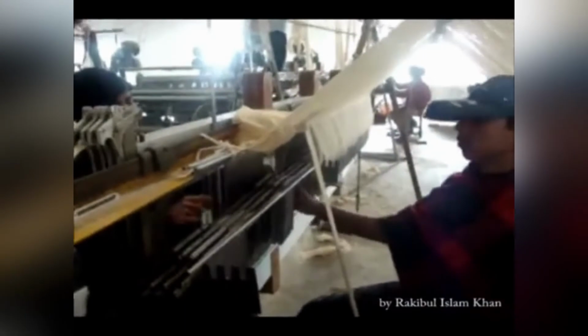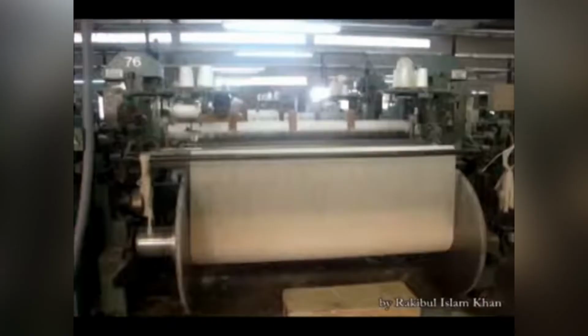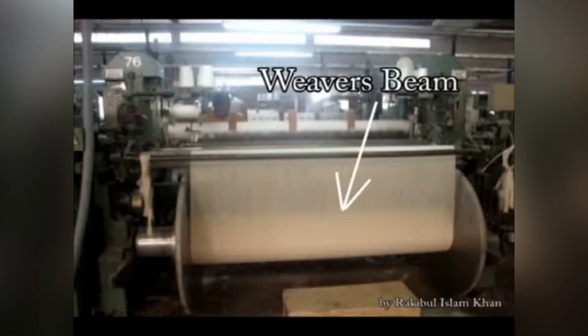Then the weaver's beam is taken for drawing and denting. The process of inserting the warp yarn from the weaver's beam through the dents of the reeds of the loom, according to the fabric design pattern, is called drawing and denting. This is the process by which the design of the fabric is set. After this process, the reeds and the weaver's beam are set on the loom.